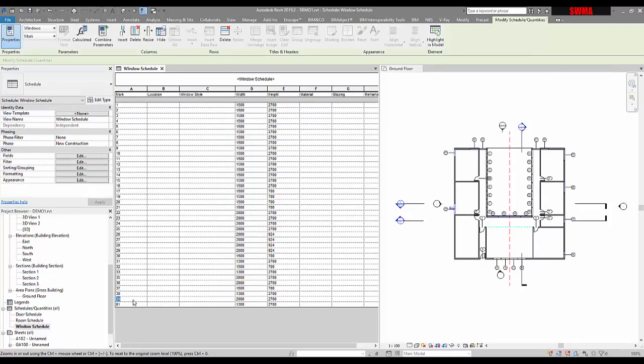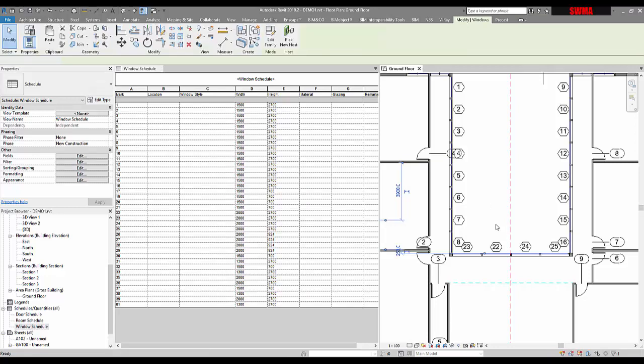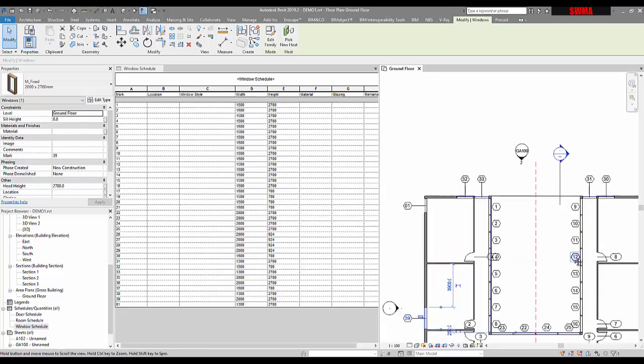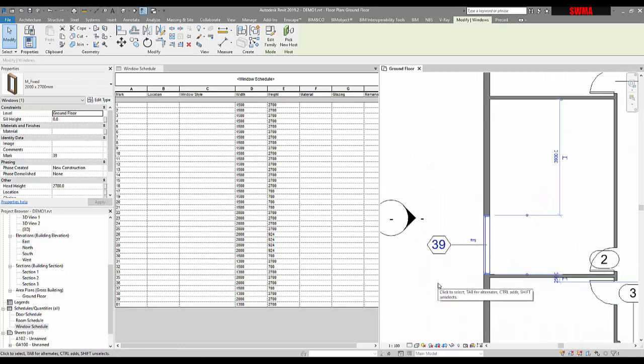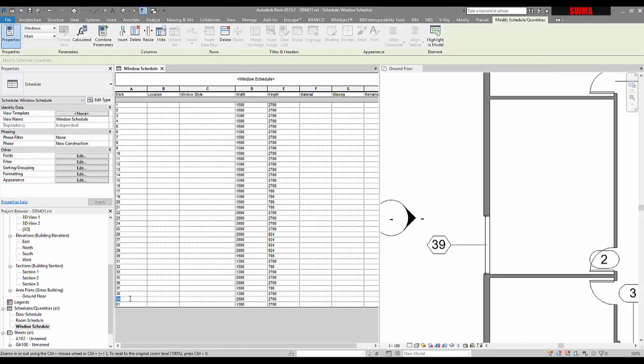This is actually bi-directional, so you can actually type in, here's door 39, which is somewhere in my model. So we can see here we have 39 right next to it. See, it's selected. So when I go here, 39 is selected, and I'm going to go to 02, and that will push it through as well. So you can actually do this from the spreadsheet here and drive that information.